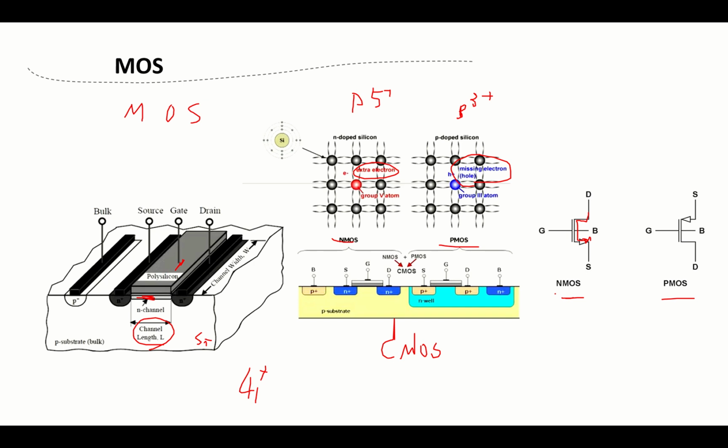So let's focus on NMOS first. For NMOS, here we dope phosphorus in those regions, which we do through implantation or epitaxy. Then they apply a voltage on it. When we apply a voltage, originally we have a threshold voltage VTH. If VG, which is the voltage on the gate, is larger than VTH, the device will be on. But how? Originally, here's the device.